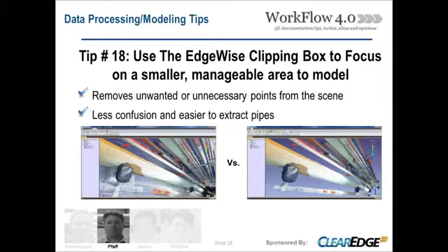Also, I want to mention, back on that last tip, as far as bringing in pipe models, you may want to look into using work sets to install your models. We found that when you bring in the piping, a lot of times the client will want it prior to its being through QC, just to have access to what's going on in there.